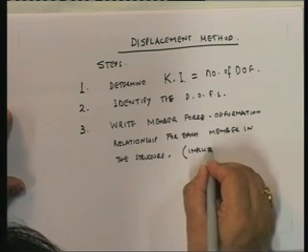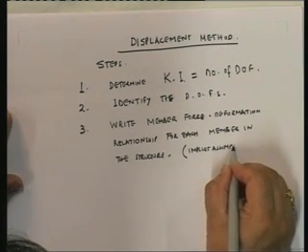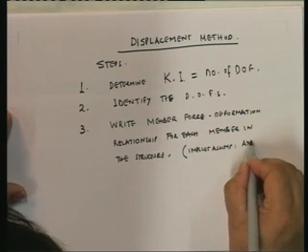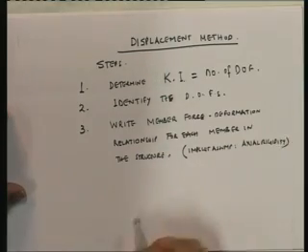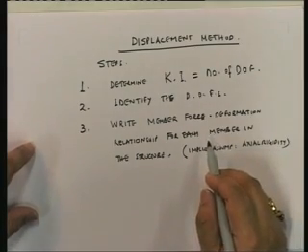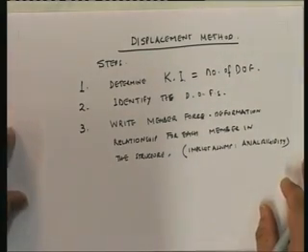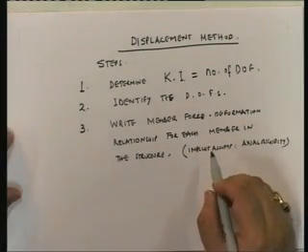Implicit, it is not required, but we are making an implicit assumption of axial rigidity. This is implicit. Okay, so therefore the force deformation relationship essentially becomes moment rotation relationships. Now you may not be able to write this if a member is flexurally rigid also, just like we saw previously you had member BC which was flexurally rigid. We could not write the member force deformation relationship for that.